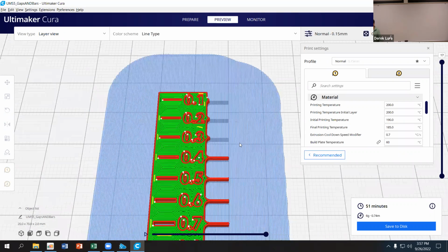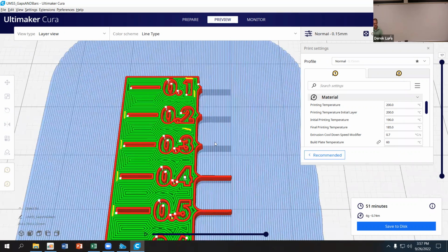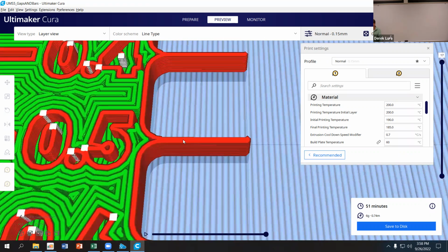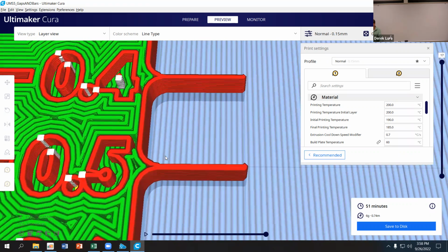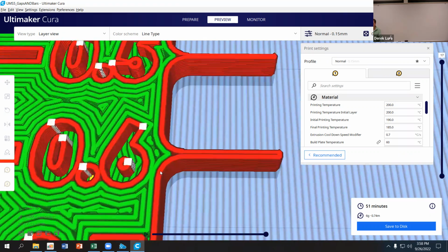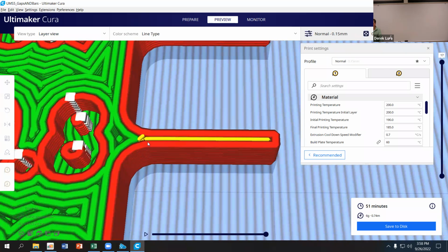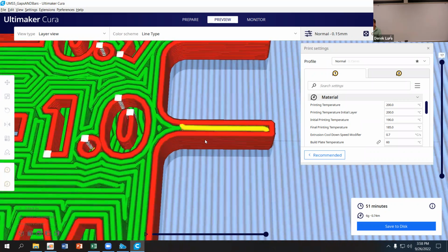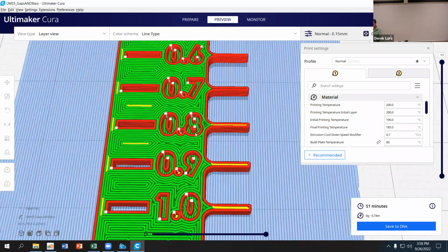And you can see that if I make a line that is too thin, this one is 0.1 millimeters, 0.2, 0.3, 0.4. Remember, I have a 0.4 millimeter nozzle, and the 0.4 millimeter one has a single wall. And I can see down here, as I go to 0.5, it actually is doing a double wall. They're just overlapped. Then same thing, 0.6, 0.7. Then at 0.8, I actually have the two walls, and I have a little bit of an infill in between those two. And then the 0.9 and then the 1 as we go down through it, right?